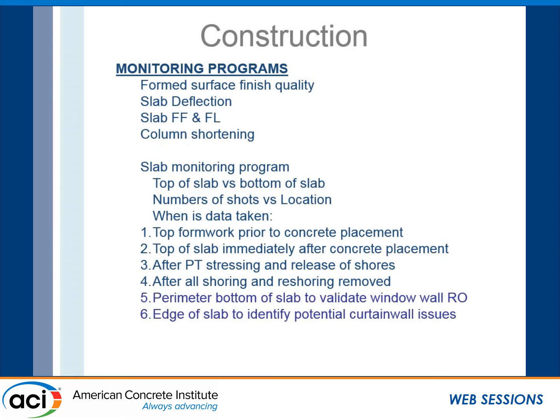We measure the top of formwork prior to concrete placement, and the top of slab immediately after concrete placement but prior to PT stressing. We go back and take shots again after PT stressing and the release of the shores. And then after all the shoring and reshoring are removed, that's typically about 30 days.